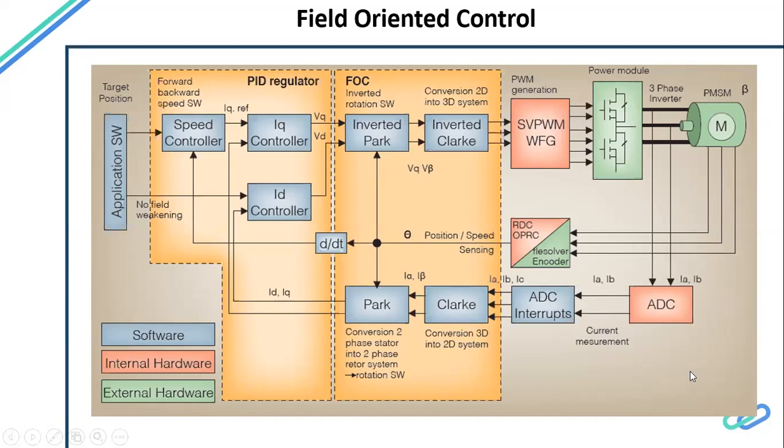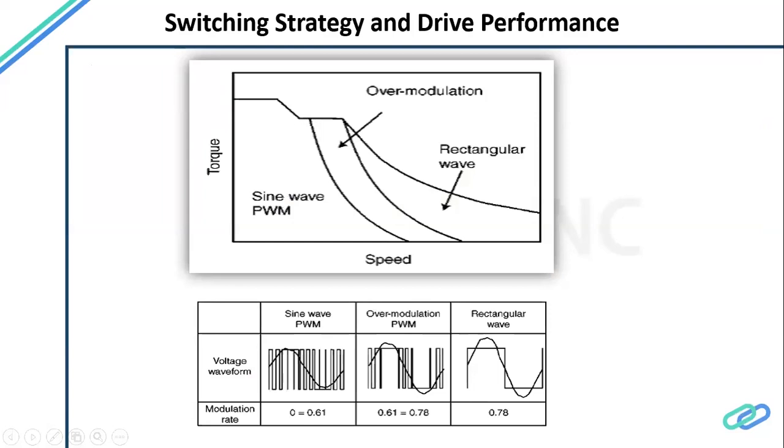We will be doing a deep dive on all these different elements that I am talking about now, and this all will impact the overall machine. Okay, the speed, you see the speed here. We are very much limited by this topology. If we do some more modulation by injecting, say, third harmonic, we can do better and give maximum speed, right? So the same motor can behave in a different manner when we introduce this machine to different switching topologies, right? So as a machine designer or an electric drive person, we should also look into these aspects.